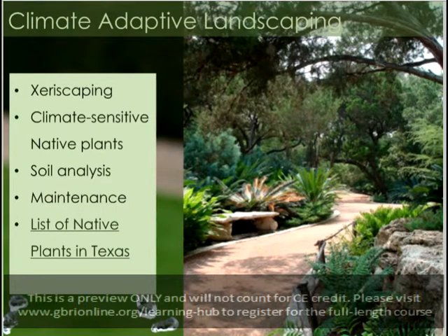The practice of xeriscaping involves selecting climate-adaptive and drought-tolerant plant species, which can reduce landscape water by 50 to 75%. Drought-tolerant does not mean that plants do not need water, but they do require less and are generally very easy to maintain. In addition, xeriscaping also provides natural habitat and pays back over time due to less demand for water, fertilizers, and pesticides. Xeriscaping can also involve the use of non-vegetative landscaping, such as rockscapes or dry landscape gardens.